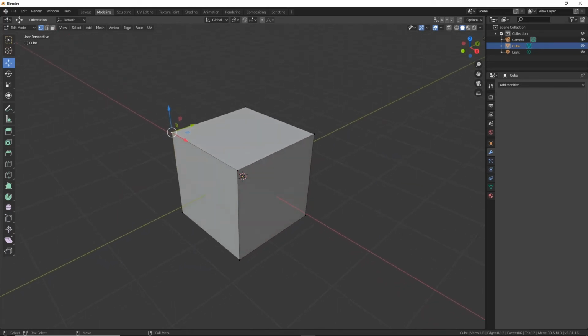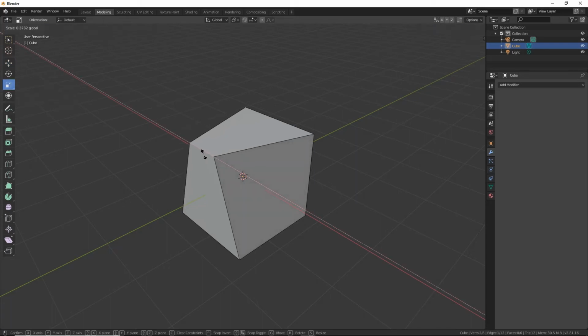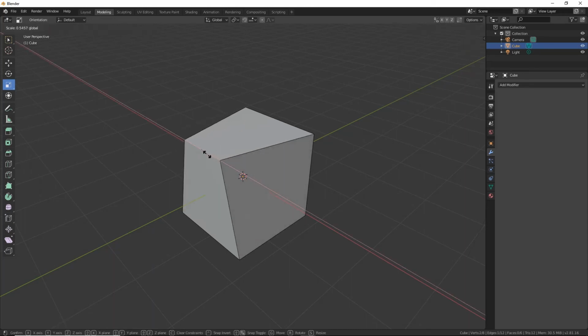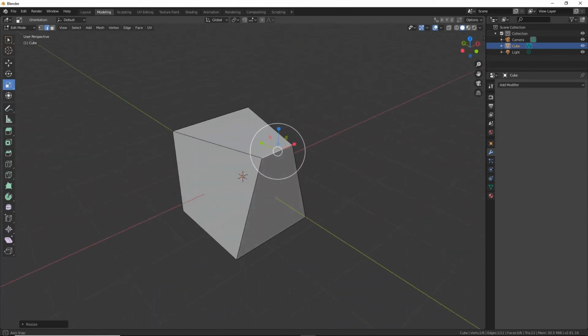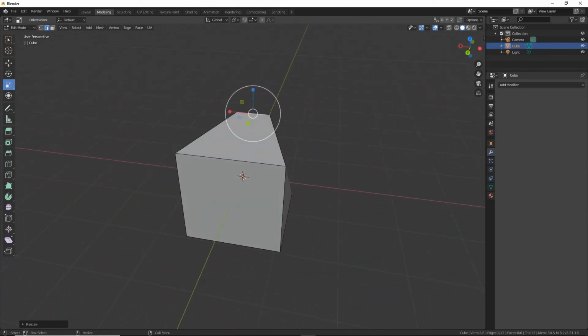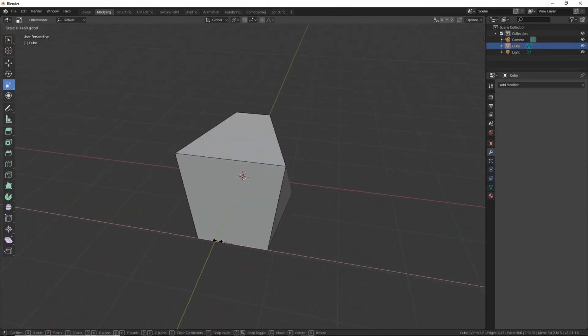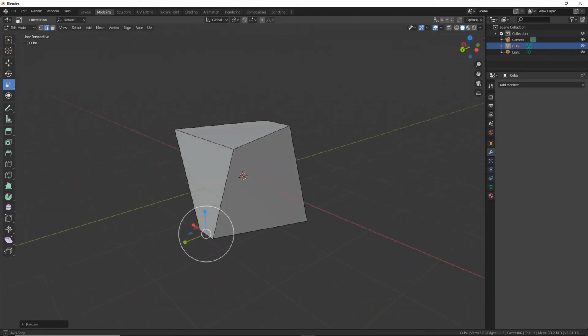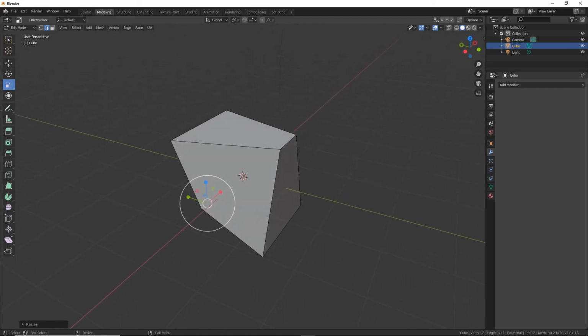What else can we do? Well, let's say I want to select the edge. I'll press 2 and select my edge just here, and then maybe I'll use a scale tool, shortcut R, and I can just scale in an edge maybe and make it smaller. Remember, you can always press Ctrl Z if you don't like the result. And this is how you start off doing the very, very basics of 3D modeling. See? We've created this interesting and complicated shape.